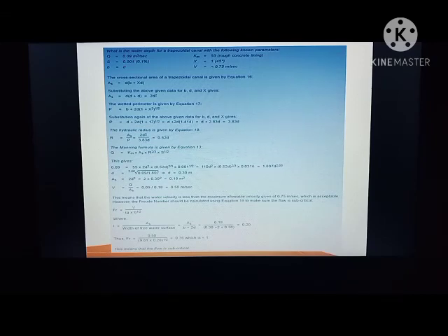is equal to 55 multiplied by 2D squared multiplied by the quantity of 0.52D raised to 2/3 multiplied by 0.001 raised to 1 half, and we get 110D squared multiplied by the quantity of 0.52D raised to 2/3 multiplied by 0.0316, which is equal to 1.807D raised to 2.66, and D is equal to the 2.66 root of 0.09 over 1.807, and we have the result of D equal to 0.30 meters.